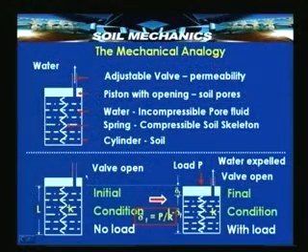So, now if we go further, we will find here the first stage is a stage where the valve is open, that means the pores are open, but there is no flow of water. Water does not go out because it is in complete equilibrium under the hydrostatic stress that is acting on it due to its own depth. So, this is an initial condition where there is no load, the valve is open, the soil is saturated, there is a spring and the spring remains in its uncompressed state.